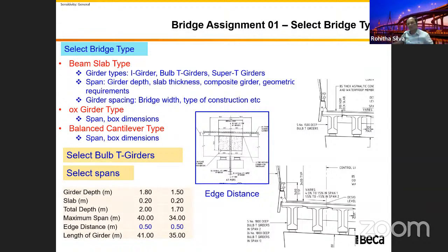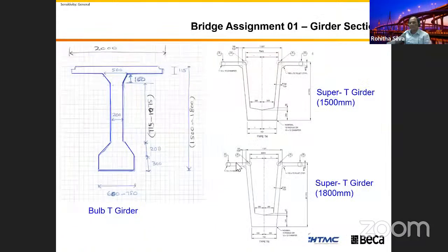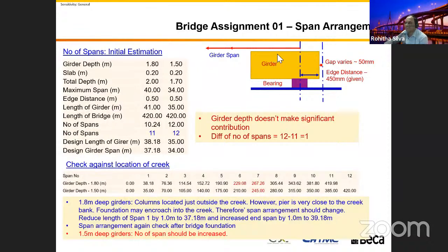Sometimes these are already in the guidelines. You can find it. Then the H distance I gave there, the H distance of the girder, I gave this distance, center line of the bearing to the back end of the girder. This we need for the force transfer mechanism to the strut tie model. You just need this extension in here, the minimum 450.